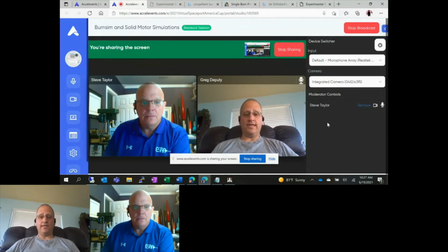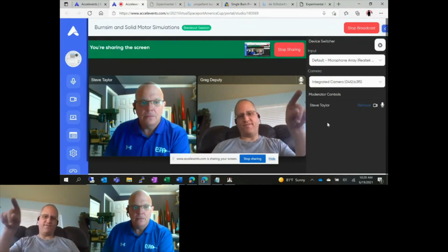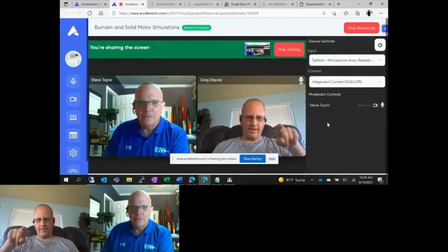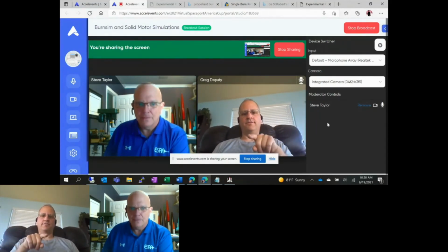And also when you get that data, in a perfect world you'd get a nice up, flat, down. If you get that, you've got great data, but that typically doesn't happen. You'll usually see you've got your igniter, and a lot of the time we've tried things like copper thermite and other things to get that burn going, and you end up with a pressure spike at ignition, and then it levels out, and then if it drops off, that is a good indicator that you got that whole surface lit all at once.